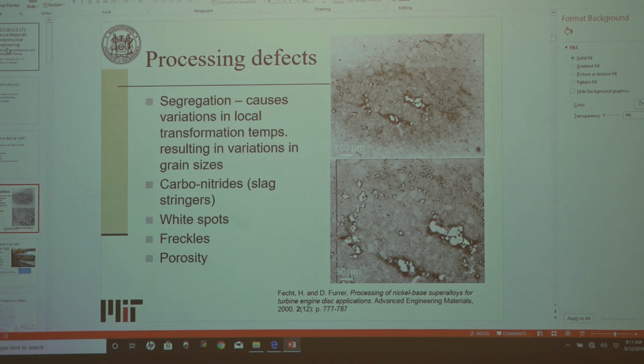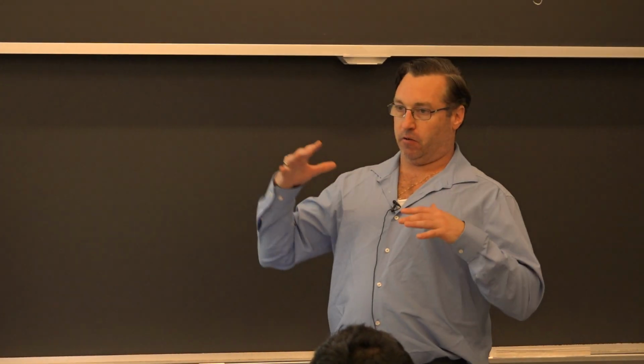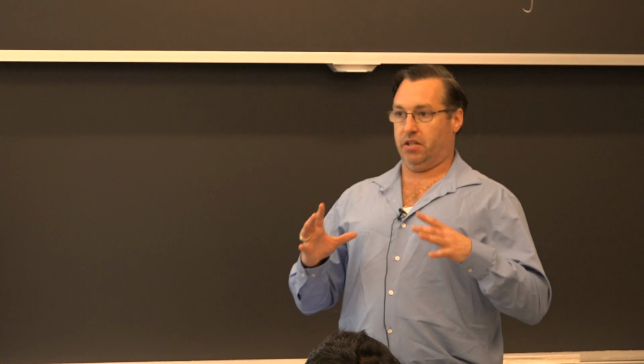So in the melt stage, if you don't have alloys that can be in perfect solid solution with each other, you can get segregation. And in steel plants, this is one of the big problems. They perform a technique called hot topping of the billet. And they already know that there's segregation for steel alloys.